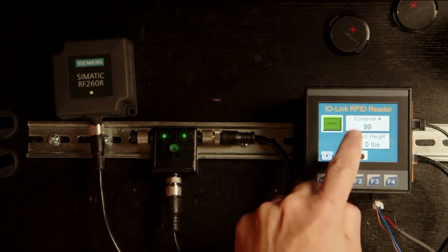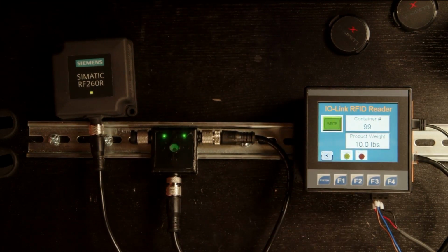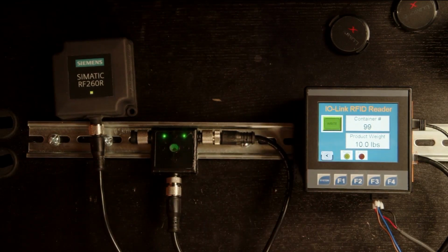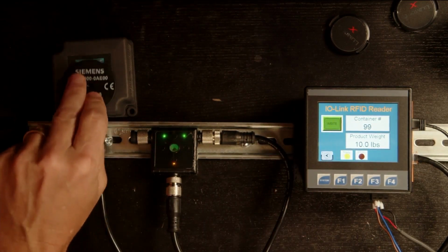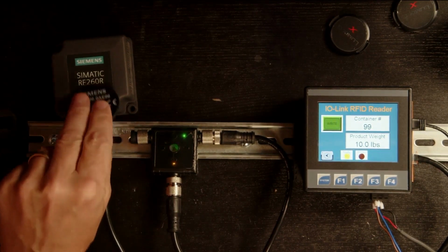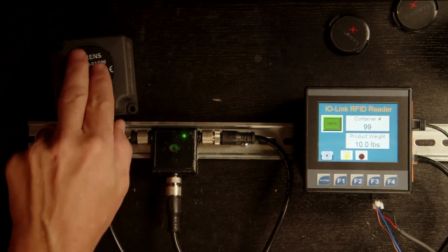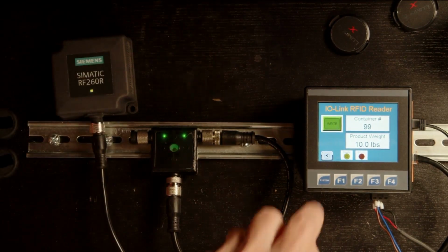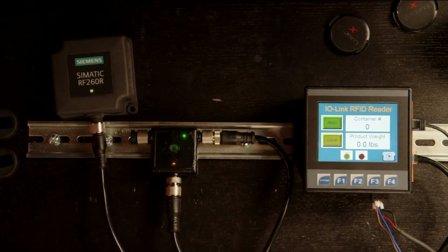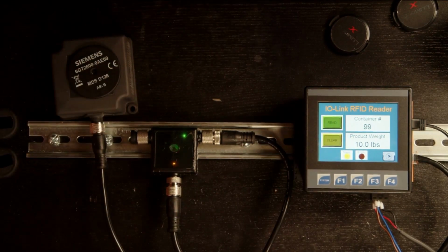And this is the data that I want to write to this tag. So those are in the appropriate memory locations in the logic code. And we're going to write a 1 or a write command in the command byte. So let me hit the write bit here to arm that. Okay, ready? All right. Put it on a second time. All right. And now let's go back and verify the data with a read. There we go.